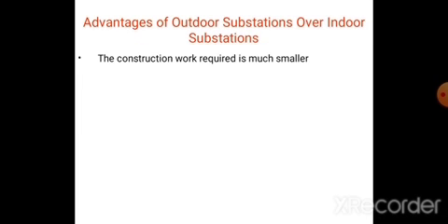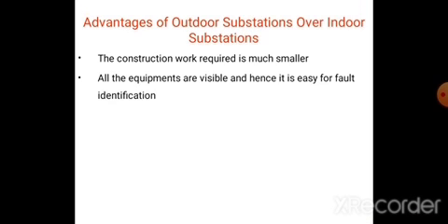What are the advantages of outdoor substations over indoor substations? An outdoor substation is placed outside, while indoor substations include underground substations. The construction work required is much smaller. All the equipment is visible, and hence it is very easy to detect faults in outdoor substations.